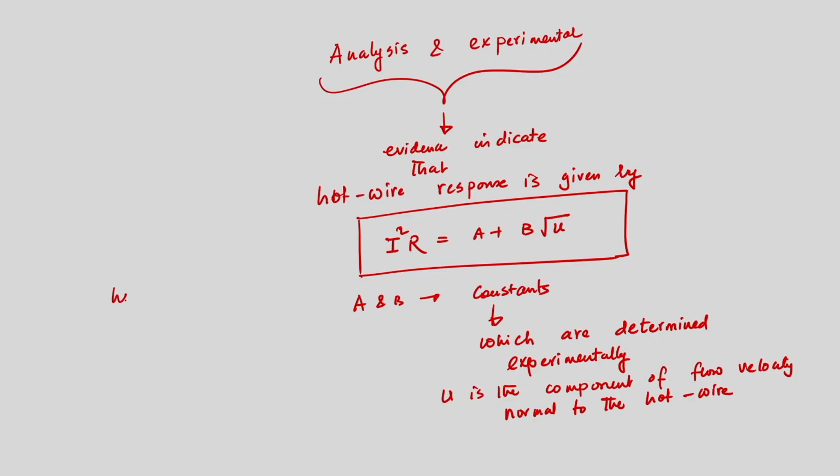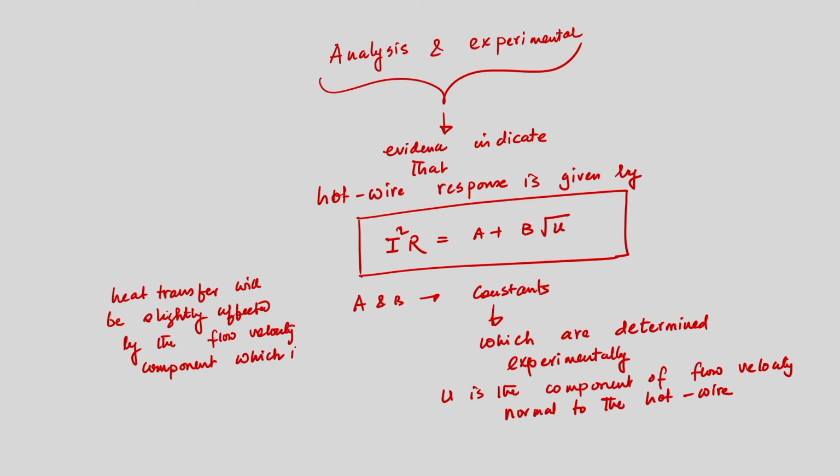But I should write at least that point that heat transfer will be slightly affected by the flow velocity component which is parallel to the hot wire.